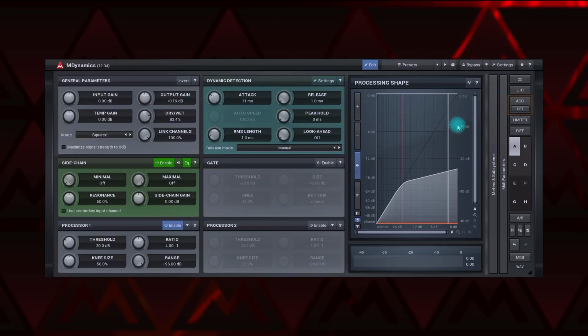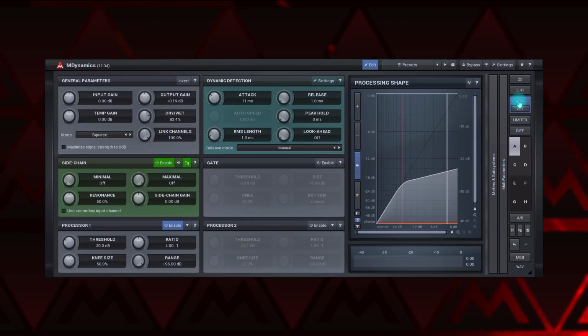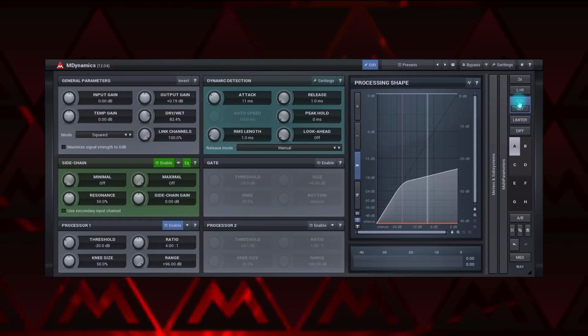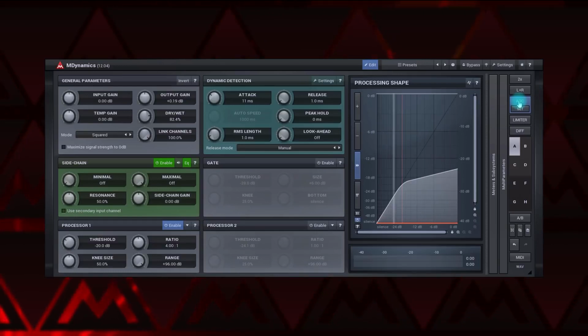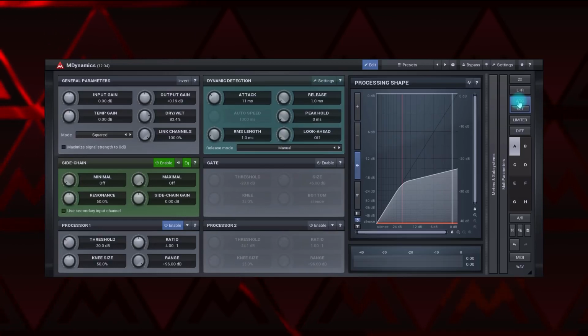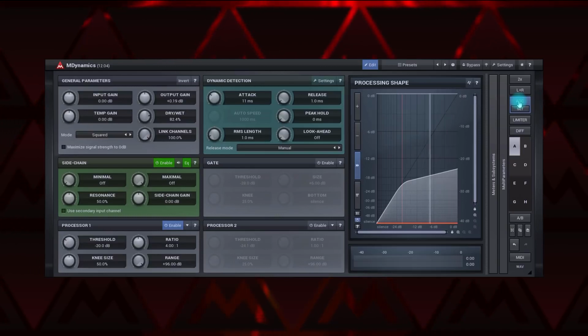The AGC button activates an automatic gain control. Frequently, processing a sound can lead to drastic volume changes that can mislead our judgment. This function can help to avoid that by keeping the loudness of the output similar to the loudness of the input. But note, this is a dynamic processor on its own, so if you use it in a compressor, for example, and there's a big change in the input signal level, these two will work against each other.